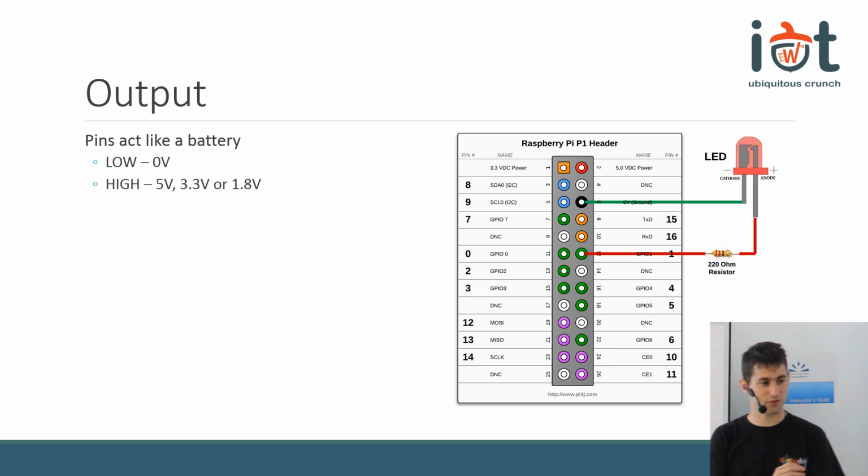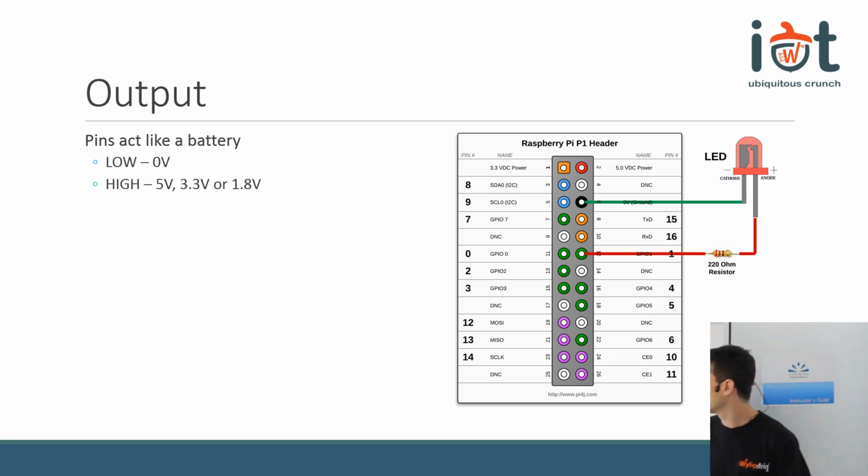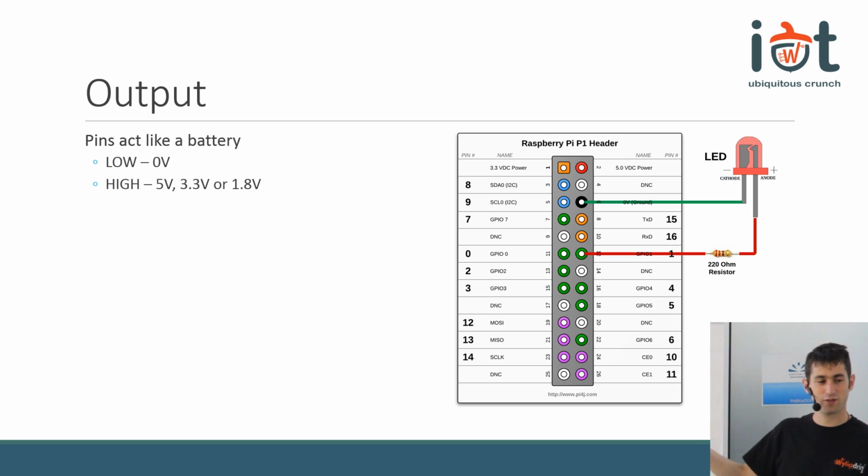Intel Galileo sometimes smokes. The chip heats up. For the Raspberry Pi, it stops. I think Edison is also stopping. But just to be safe, please understand, LEDs are packaged with a resistance. Always when you use an LED, just put a resistance.